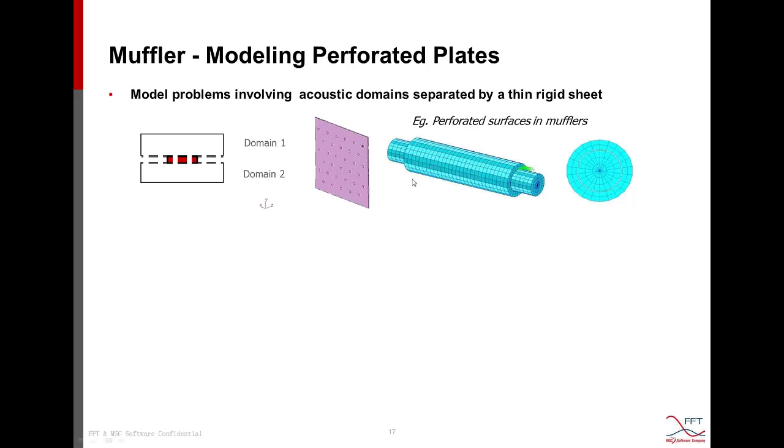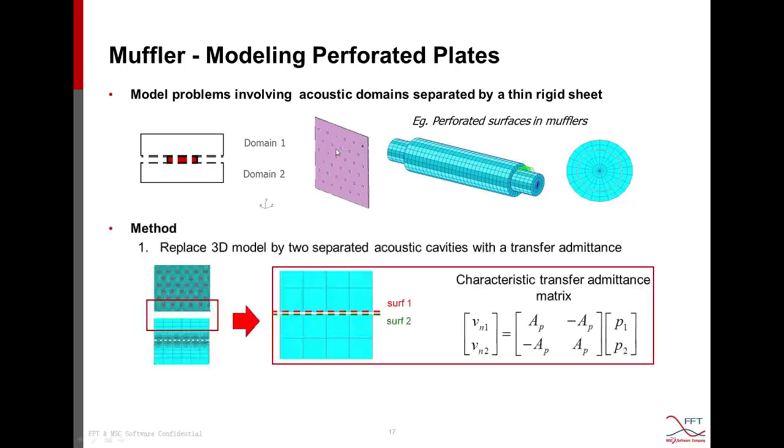So this example is a cylinder muffler, which is different from a simple expansion chamber in the sense that the central duct and this expansion volume are separated by this perforation plate. So the perforated plate is a sheet that is punched with many holes on it.